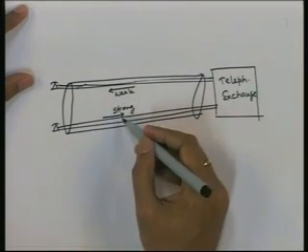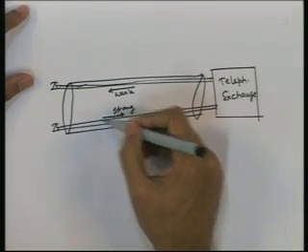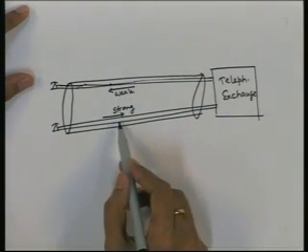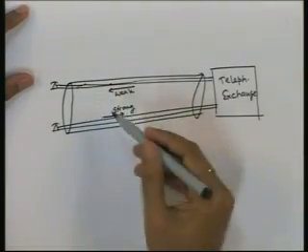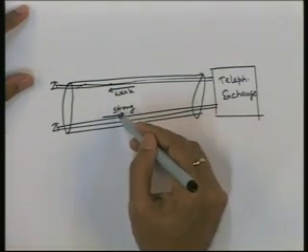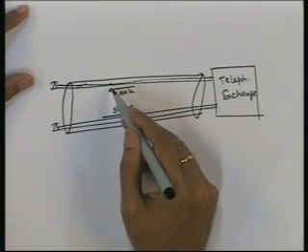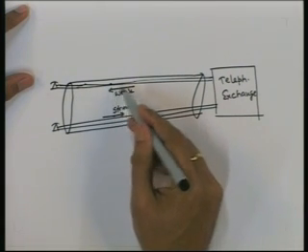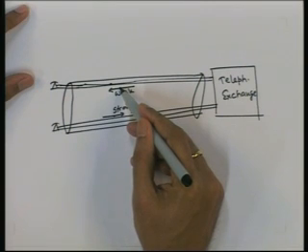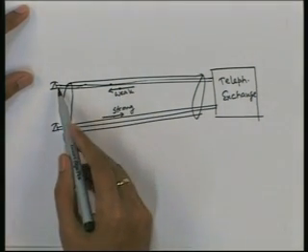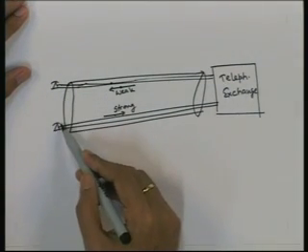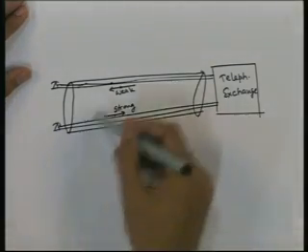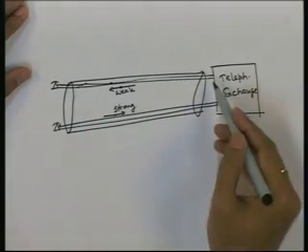and as a result this strong signal is induced into your pair of wires. The current flowing through these two wires is also inducing some current in your wire. So, there is some interference, and because this signal is much stronger than the signal coming from the opposite direction to you, the induced current from this signal itself may be stronger than the weak signal that you are intended to receive. As a result, instead of hearing the voice from your opposite end, you will be hearing the voice from here, because of induction from this strong signal to your line. So, that is what is called crosstalk. You are not hearing the voice from the opposite end, but you are hearing someone else.